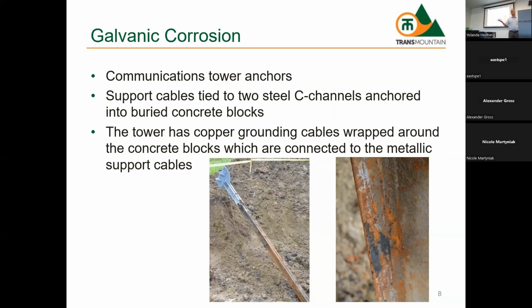Because it has no electrolyte. In atmospheric conditions, galvanized steel does not help because there is no electrolyte. Theoretically, if everything would be immersed, the zinc would be consumed completely before something else happens. But here it doesn't, because you get the corrosion on one side, but the zinc on the other side doesn't care because there is too little electrolyte flow. So that's the problem with using galvanized in atmospheric conditions. If it would be immersed, it would work. Okay. Well, that's what you would think.